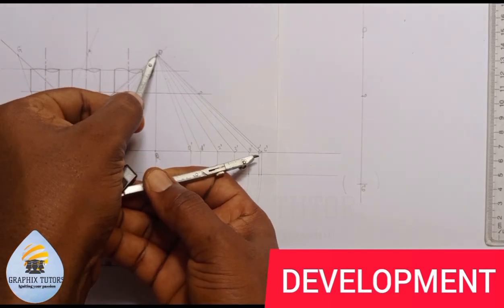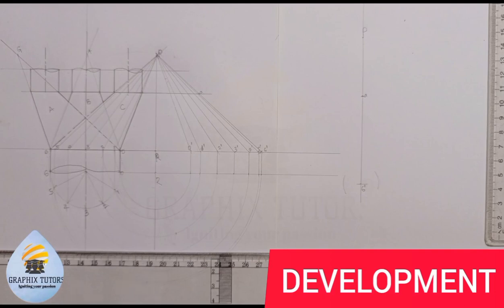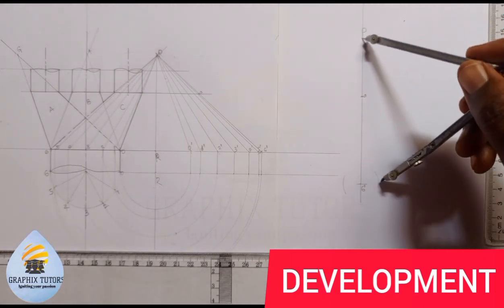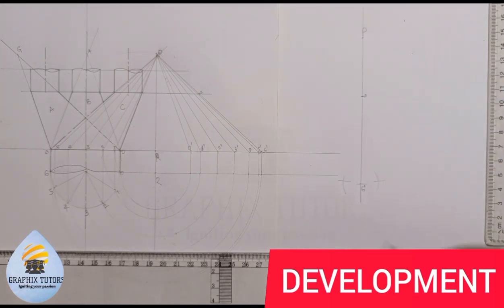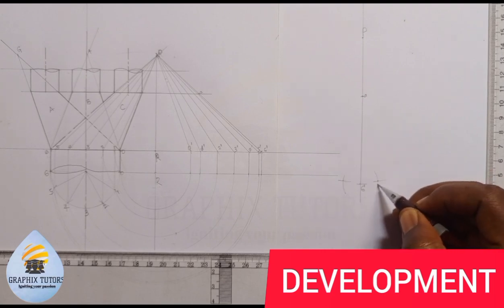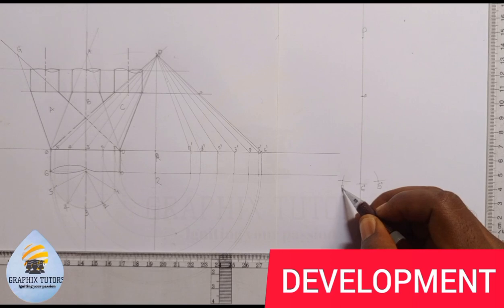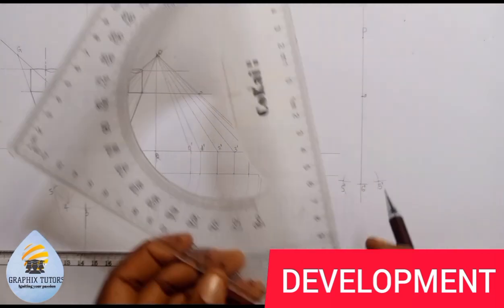The next point, 5. Can you see that? And I will come to P here and I'll cut those arcs, left and right. So the points where they meet, these 2 points will be my point 5 prime and my point 5 prime. Can you see that? And I will draw my line from those 2 points this way.